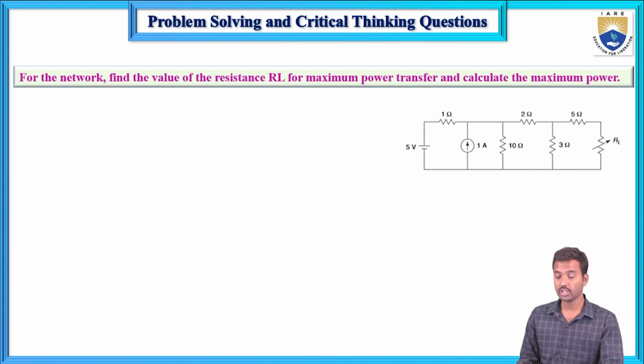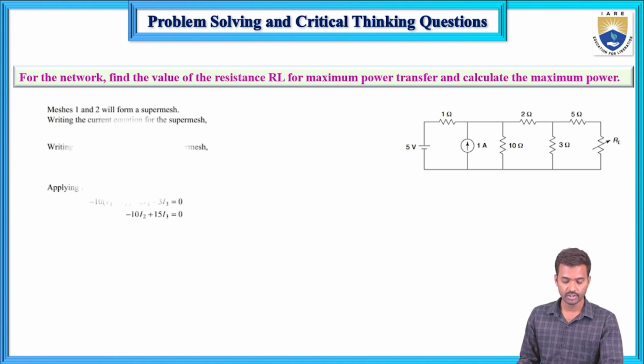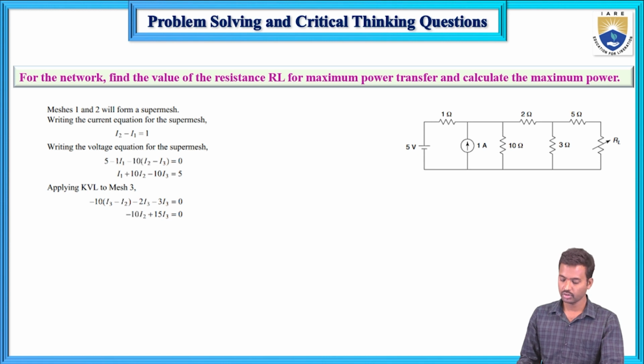Same maximum power transfer theorem. Here three problems we are solving. So same thing here. First calculate the VTH, Vs. So this is I1, this is I2, this one is I3, and I4 current is 0. So now here remove the load resistance and calculate this open circuit voltage.